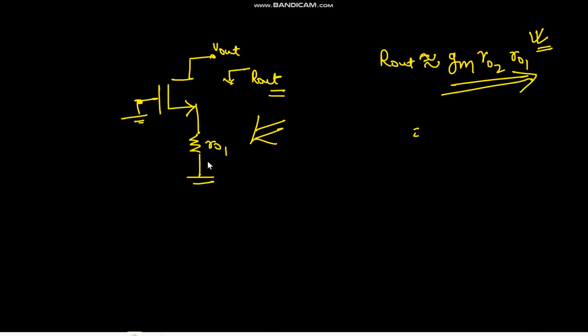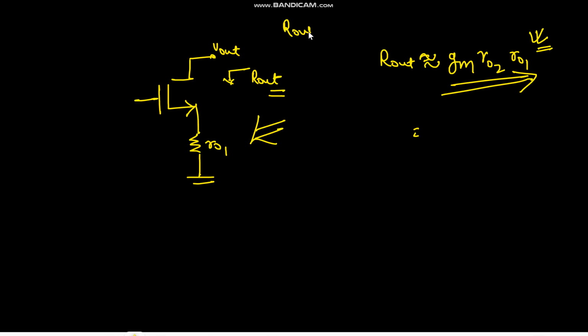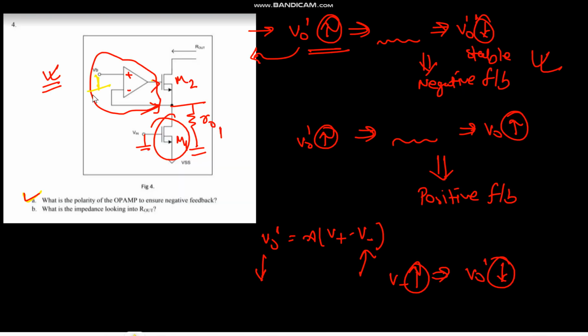Okay. Look, just now I thought about this circuit, and there is one error I can find. I don't think I can make this one short circuited, right? Why? Because for finding the R output, I will apply one V output here and I output here. So my R output would be V output upon I output, right? Now this I output is flowing through this resistor and would give me I output into R output 1 voltage here. I can short circuit this one VB voltage, this DC voltage I can short circuit.